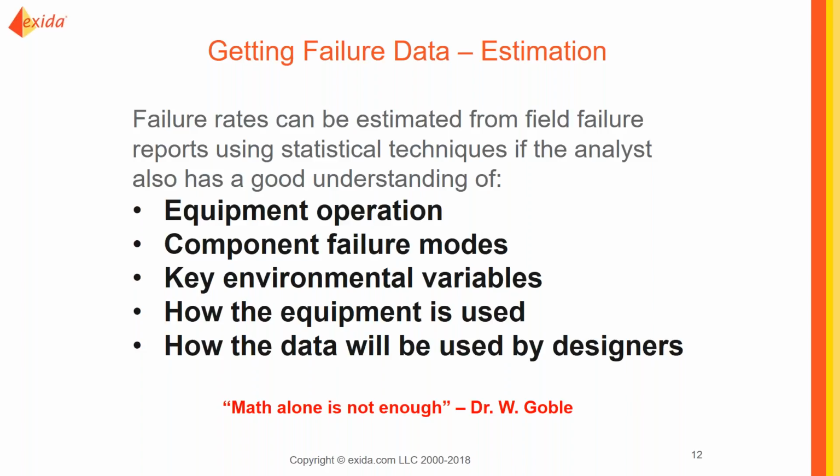Well, here are some bullet points in front of you to help prove his point. Sure, you have your statistics, you need those, but what about the equipment? How is it used in the operation? And there are different component failure modes. Does it fail safe, fail dangerous, fail undetected, detected? And then you have environmental conditions. Where are you using this? Is it in the desert? Is it in the jungle? Is it offshore, onshore? How is the equipment used? And then what about the data? How's that data going to be used by those designers? Is it going to be used correctly? So all of these things now become a factor when you start developing these failure rates.